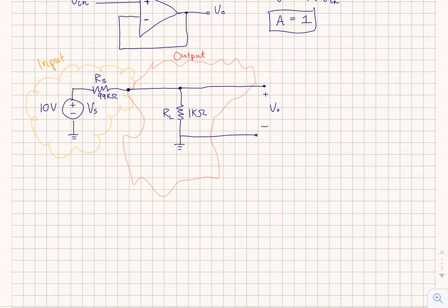Okay. Now, you can kind of break this down pretty easily and pretty quickly because you've all had circuit analysis and you should be able to do this, but you can say, well, Vout is going to be equal to Vs, and then there's a voltage divider involved, and so we're going to say that it's going to be RL times the sum of all the resistances in the circuit.